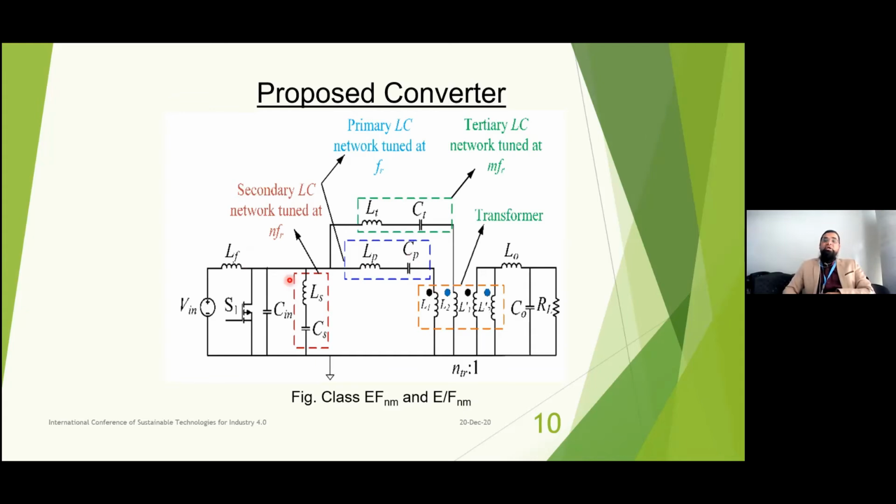So we are delivering 100 kilohertz power to the secondary through the primary resonant tank. Now this is the second harmonic. So this is the 200 kilohertz switch resonant frequency. The 200 kilohertz resonant frequency is being bypassed through this resonant tank. So this helps to reduce the peak switch voltage, but because you are now bypassing the second harmonic, you are losing a lot of power.